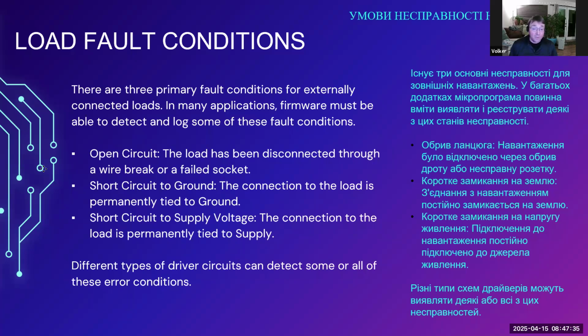So there are fault conditions that happen, and the driver circuits often need to be able to detect the fault conditions before any power is applied, or at least detect the fault condition when power is applied. The microcontroller has to check for a fault condition and, if necessary, set error flags or take the necessary steps.